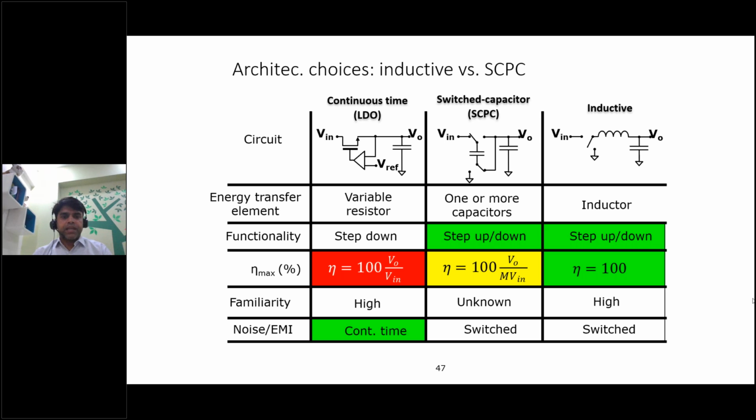So sometimes its energy efficiency is low, but it has a very good noise performance. Same thing if you go to switched capacitor circuits. This is something where there is a switching capacitor that keeps dumping some charge on a big capacitor. The first problem is that you need one more capacitor, and not just one more capacitor, it's sometimes a giant capacitor.